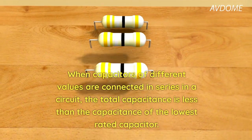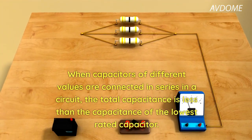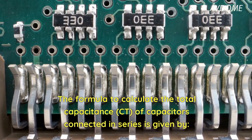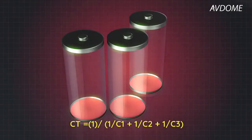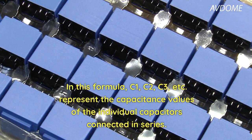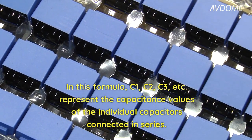When capacitors of different values are connected in series in a circuit, the total capacitance is less than the capacitance of the lowest rated capacitor. The formula to calculate the total capacitance, CT, of capacitors connected in series is given by 1/CT = 1/C1 + 1/C2 + 1/C3. In this formula, C1, C2, C3, etc. represent the capacitance values of the individual capacitors connected in series.